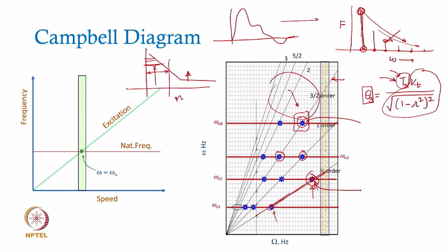And then finally, coming back to this point, this has the same point of discussion as we saw here. Suppose you have still the unbalanced excitation force m e omega square as the magnitude, e to the power j omega t, and we know that the higher frequency components which are being plotted here are all corresponding to higher frequencies of the decomposition.